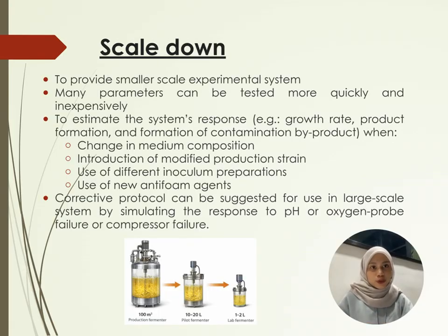So now let's move to the scale-down reactor. A scale-down reactor is a smaller reactor that is mainly used for research and testing. It allows researchers to test many parameters faster and at a lower cost compared to the large-scale system. For example, we can study the effect of changing the medium composition, using a different strain, or adding a new antifoam agent. From this, we can observe the system response such as growth rate and product formation.